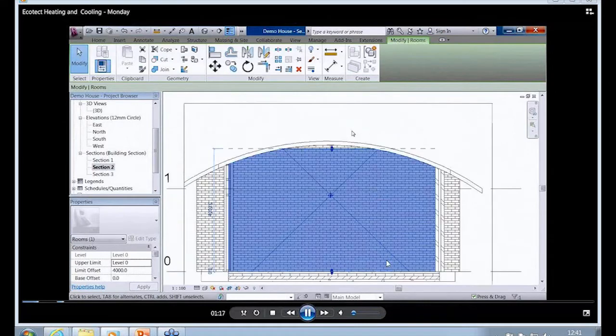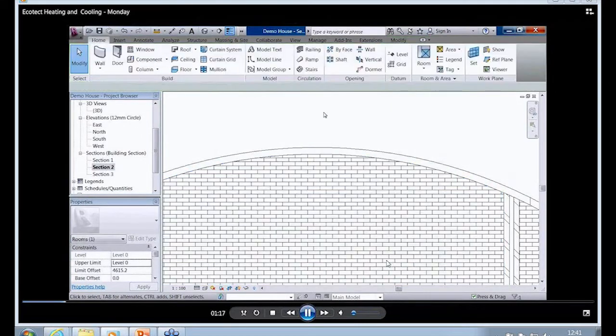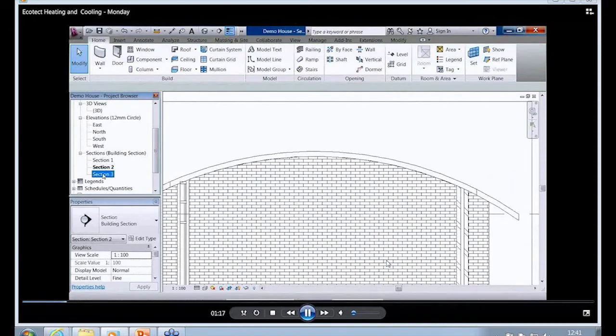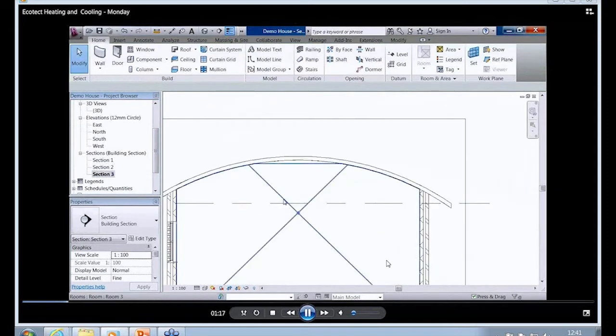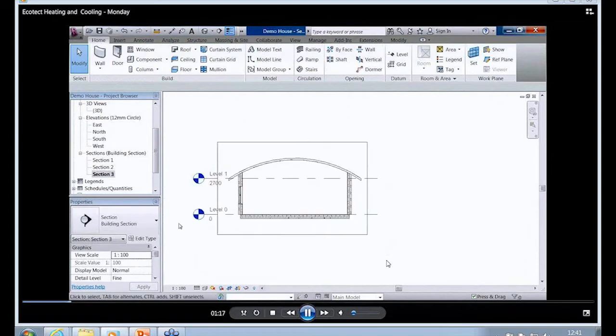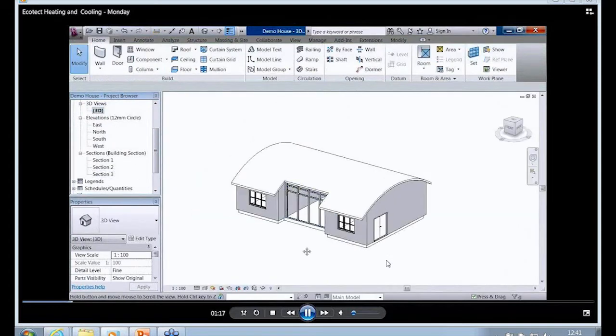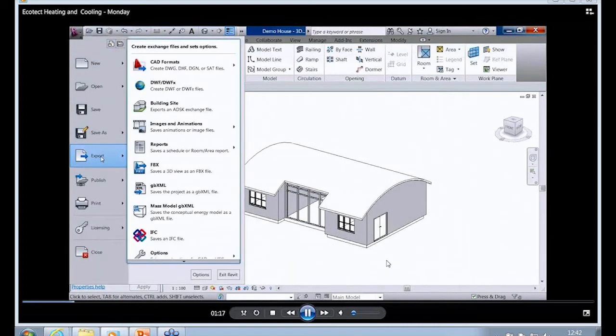So here you can see the room, the height of the room is such that it doesn't fully extend beyond the roof, so this is something you might well need to check. And then lastly, for the third room, we'll do the same. So just extend these rooms fully upon the boundary. Okay, so now we'll do the export.